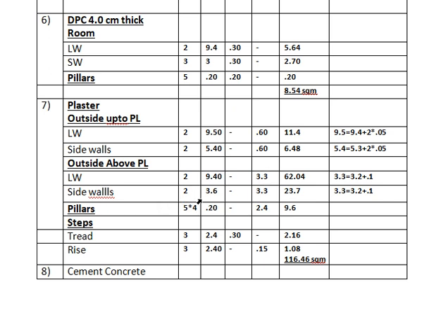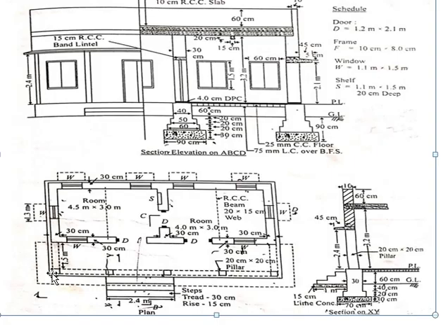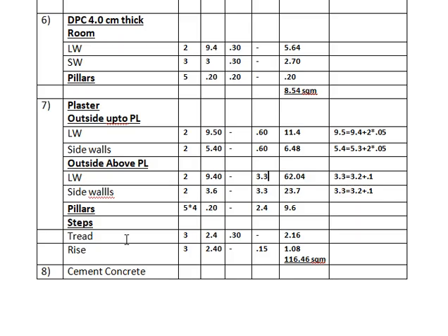Now talking about the side walls, since we are above plinth level and the veranda is only up to the plinth level, the side walls will be 0.3 plus 3 plus 0.3, so it will be 3.6. Again the height will be 3.3.